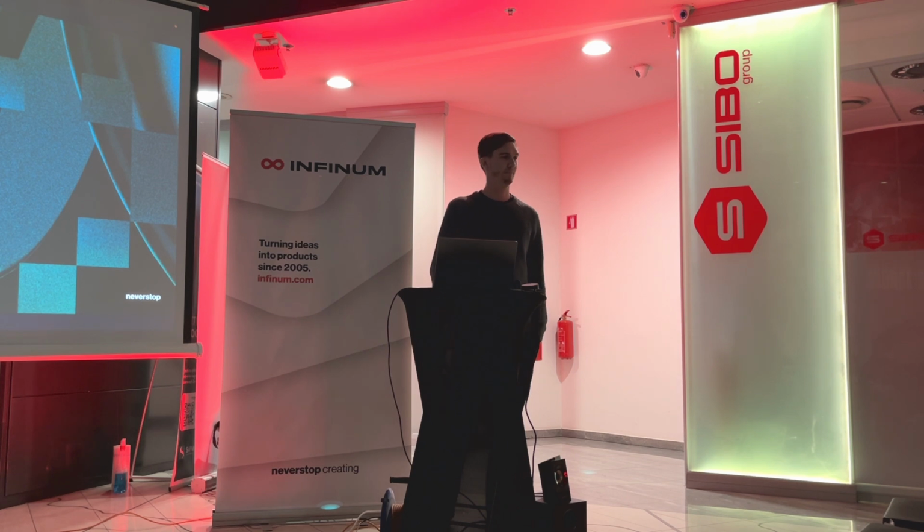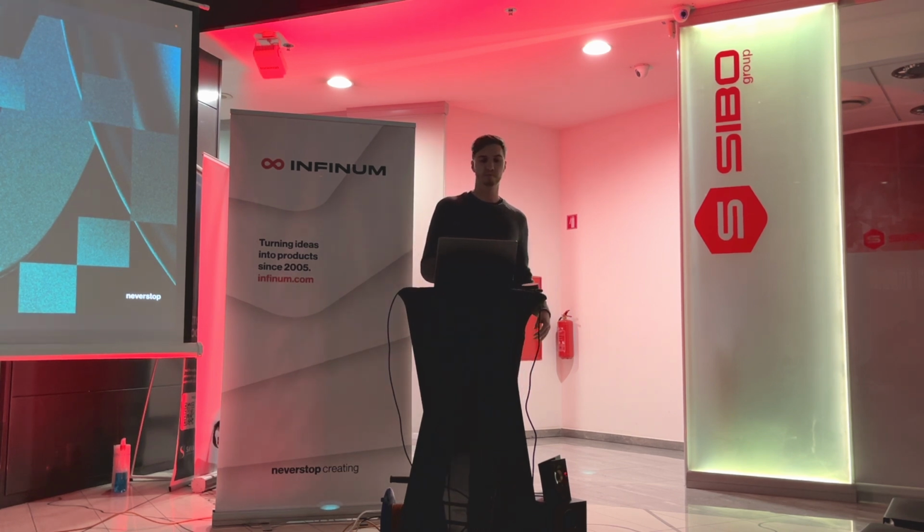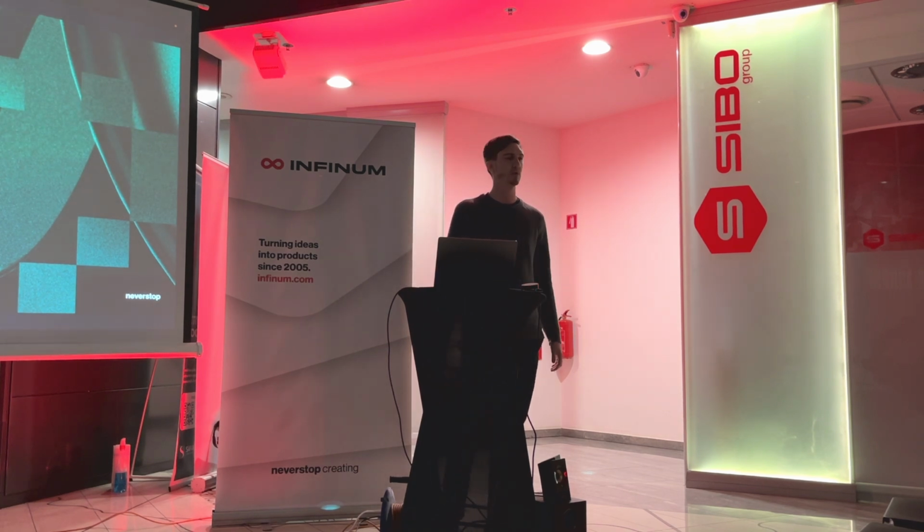What happens with how you test for different screen sizes, because each manufacturer has a different screen size? Can you set it up in your simulation program? Yes, we actually. Sorry. Oh yeah, how do we handle these different screen sizes if we can set them up in our development environment, basically? Yeah, so essentially we have this Android Automotive box, and that box is already set up to use the correct resolution, or you could even set this through ADB, right? I think you can set the resolution and everything, but yeah, we can set up the exact resolution and screen size, so we can actually test properly even with this.